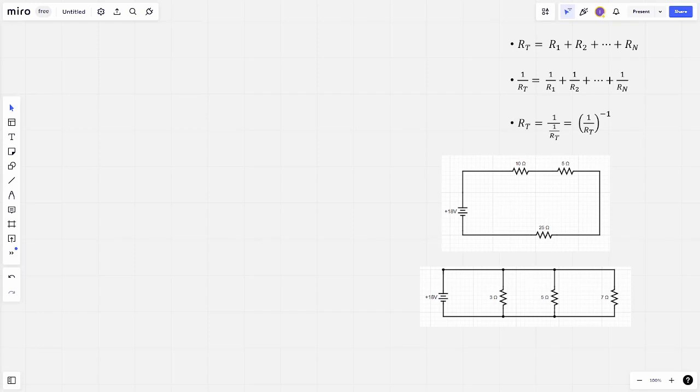In this session we're going to be covering resistance in series and parallel circuits. So here what I've done is added a key to the right hand side. What we've got is 3 bullet points. The first bullet point represents the series circuits. So this here is series. This bullet point says the total resistance, that's RT, is equal to the summation of all the resistance R1 plus R2 plus R3 plus anything else, all the way to the end resistance in series.